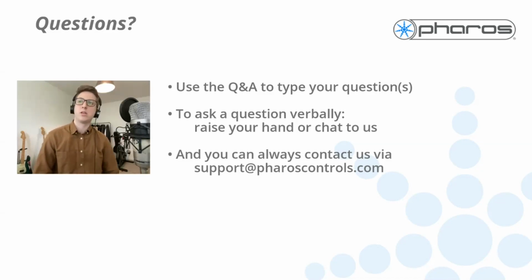No, I think you were spot on. The way Faros Designer supports integration with Lutron is via the Telnet module, and I know this has been verified and used on projects. If you would like to receive an example file of how this works, I know we have that available. Please just contact us via support@faroscontrols.com, because we should be able to get that file to you.